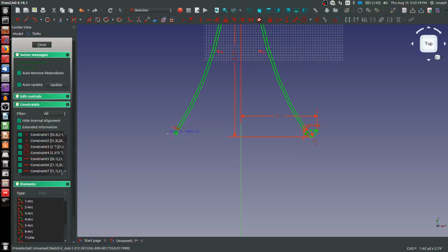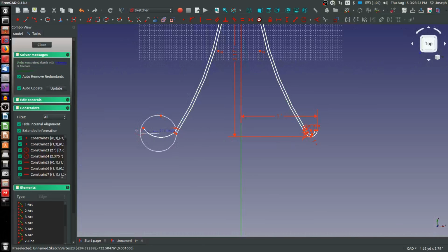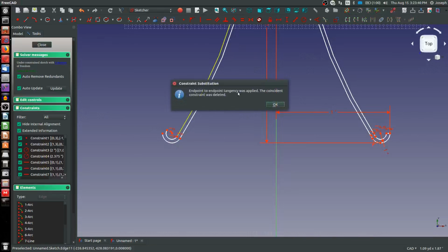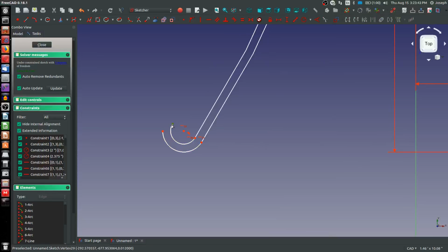Now, let's go for a rim point arc. There we go. Grab the two center points of those arcs, merge them together. Again, that makes it concentric. I can even make this horizontal, and we can add a tangent relation with the T key. Horizontal between these 2 points and horizontal to its center point.